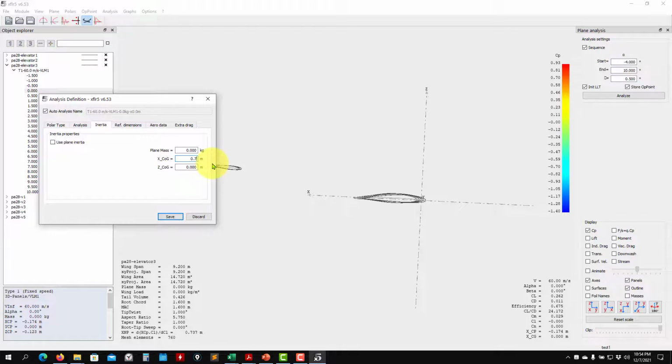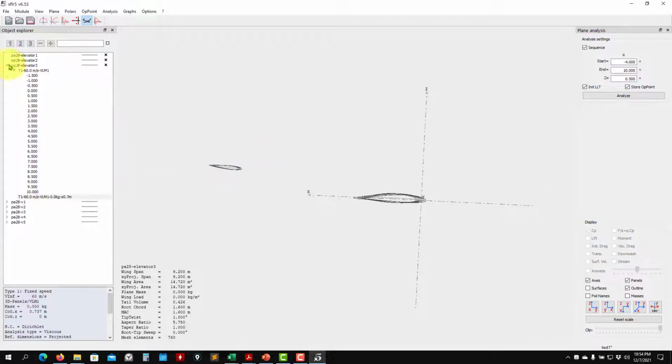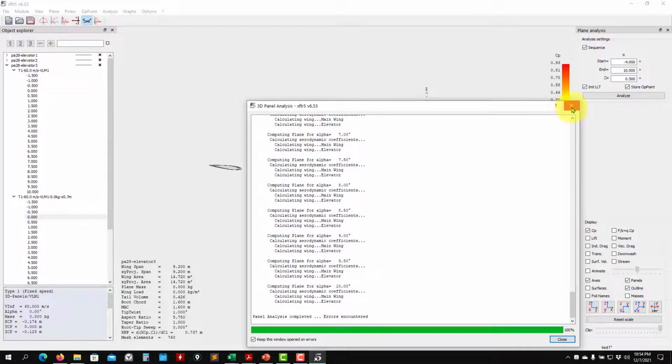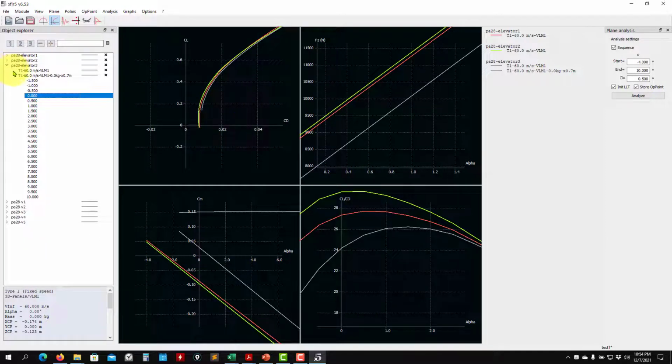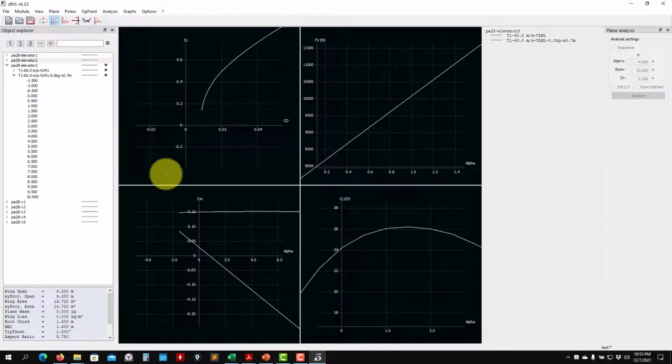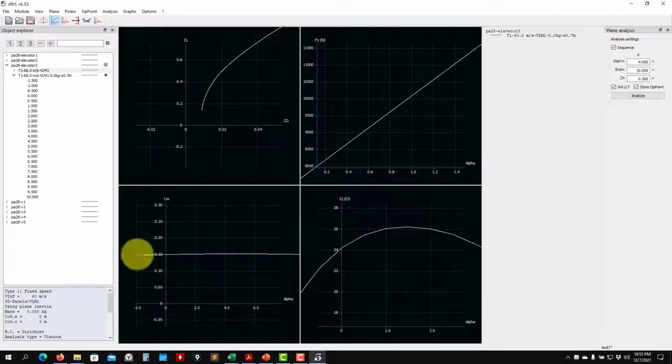0.737. Actually, there is an airplane, 0.737. So if I run now, I just move the center of gravity. You already see the new one. See that the center is the neutral point. See that the moment doesn't change as a function of the angle of attack. So dCm over dAOA, or dCm over dCL, is equal to 0. It doesn't change. This is the neutral point.